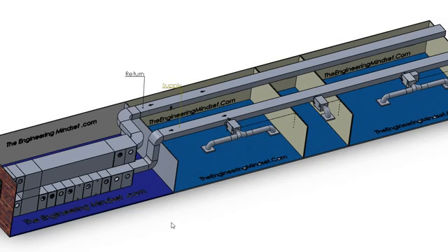Now, in a VAV system, the air coming out of this supply AHU and through the supply duct is running at about 13 degrees Celsius or 55 degrees Fahrenheit, and that will flow all the way through to the end of this duct here, where each of the rooms can feed off of this and take some of that 13 degree or 55 degree Fahrenheit air as needed. That air distributes into the room through these diffusers, spreads across, and then,